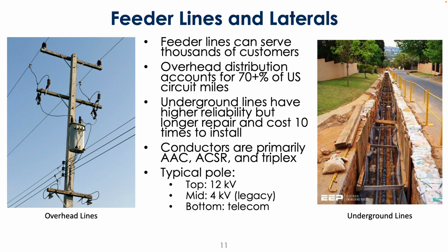but the maintenance and repair costs and the deployment of these things are a lot more expensive. We did talk, right, about undergrounding in transmission systems, and we looked at some of those costs being about 10x higher. And the same is true for distribution. You can imagine that putting up a pole versus doing this kind of trenching has fairly different construction costs.